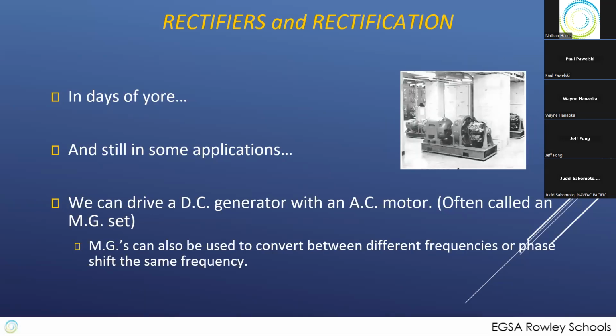So other places you're going to see this, the radar installations, pretty much everything is 400 hertz in the radar installation itself. And the design within the installation is pretty much the same, whether it's being put in Hawaii on a 60 hertz setup or it's being put in Dubai onto a 50 hertz setup. There is enough power required there that a motor generator system is used to do the conversion to 400 hertz.